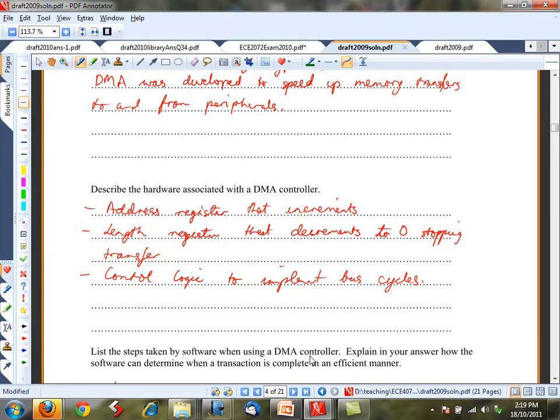So you're sitting in the lab, you've got your DMA controller running. The software has to determine when it's finished. How does it do that? You've got two answers. Yes, you've got an acknowledged signal. So what do you do with that? Yep, so you poll that, do you? Okay. So you sit there in a tight loop, say, are you ready? Are you finished? Are you finished? Continuously? Well, that's a valid answer. That's fine. Got any other answers?